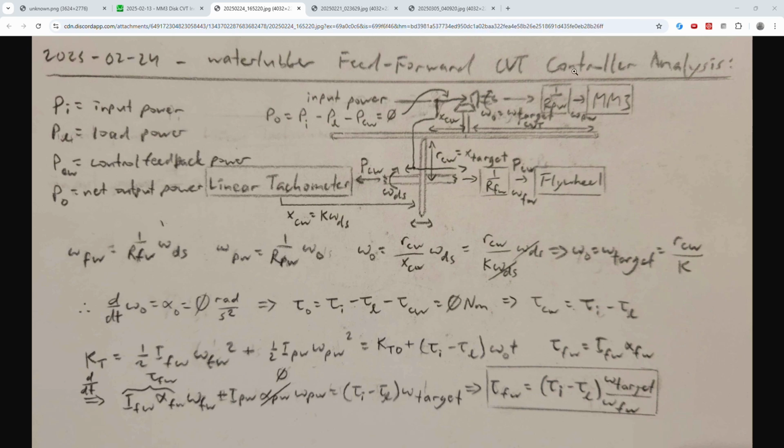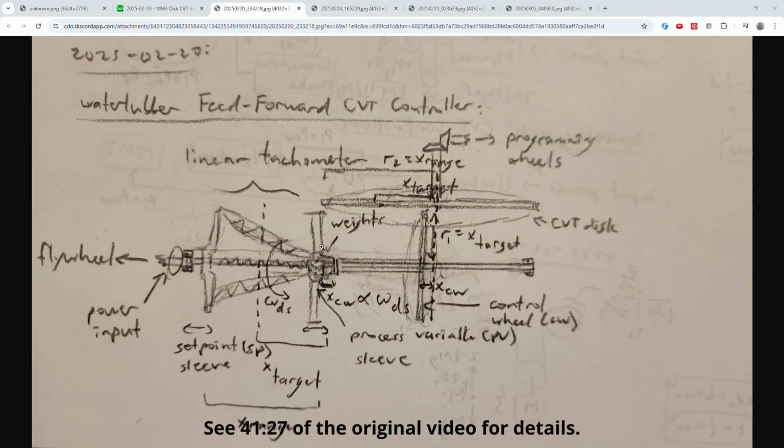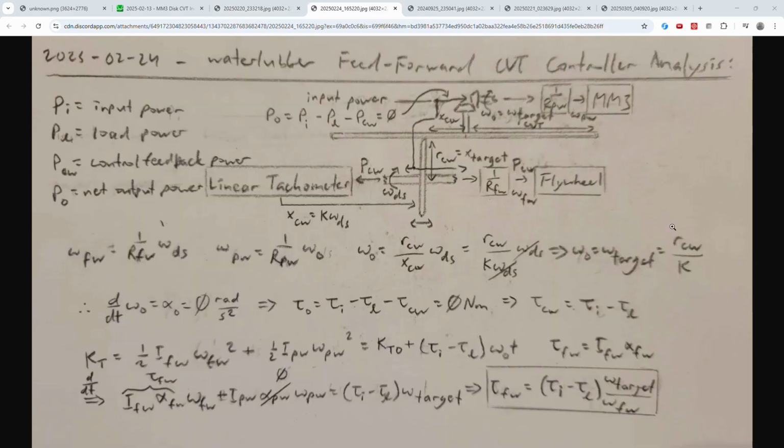The problem is that in this simpler single-disc design, the maximum energy surplus that can be stored and released depends on the radius of the CVT disc and the measurement range of the tachometer. Alternatively, a larger flywheel would facilitate smaller movements of the control wheel for the same changes in the flywheel's rotational kinetic energy. Likewise, the tachometer needs to be perfectly linear for this equation to be true, else there will be some deviation from perfect timing proportional to that nonlinearity. This can be achieved with a design like this, where the flyweights are constrained by calculated cam profiles instead of linkages.